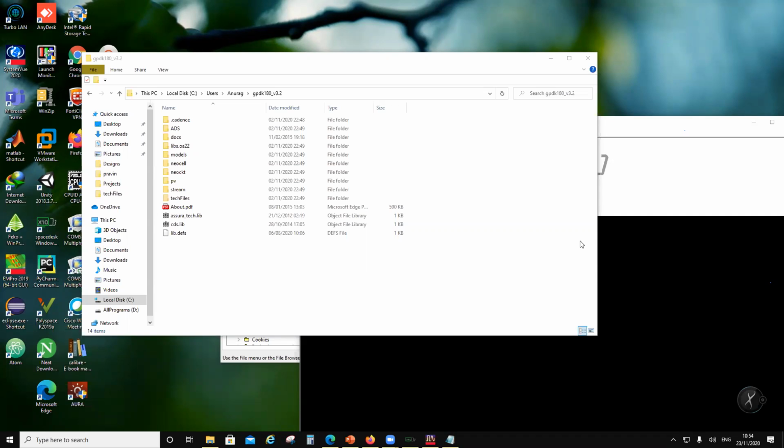Now, in EM simulations, we should know one thing: EM simulators are Laplacian solvers. That means the source, the free charges moving, are not there. Of course, current estimate is there, but you will not put charge into the substrate. You will not put charge as a source of fields. I will not say lossless, but it is a source-free medium, which means I'm not injecting electrons or holes into my volume of simulation. That means it's a Laplacian solver, so I would not be able to do actives.